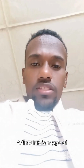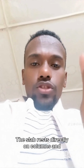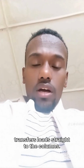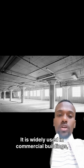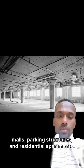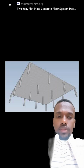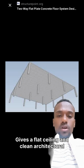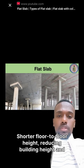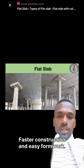A flat slab is a type of reinforced concrete floor system without beams. The slab rests directly on columns and transfers load straight to the columns. It is widely used in commercial buildings, malls, parking structures, and residential apartments. Key characteristics: no beams between columns. Gives a flat ceiling and clean architectural appearance. Shorter floor-to-floor height, reducing building height and cost. Faster construction and easy formwork.